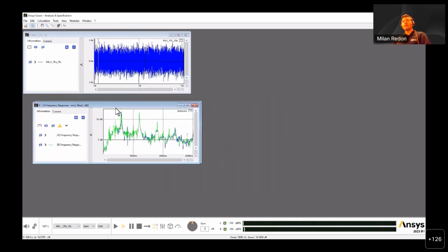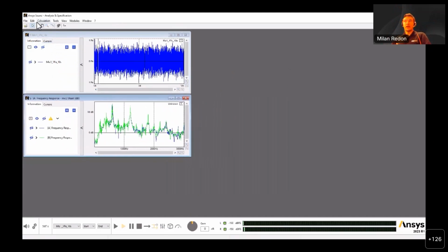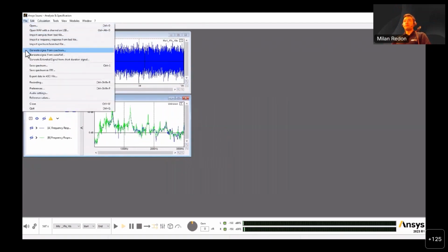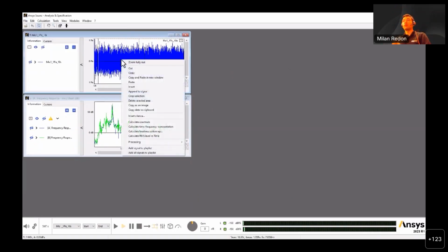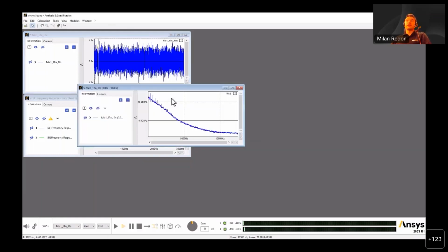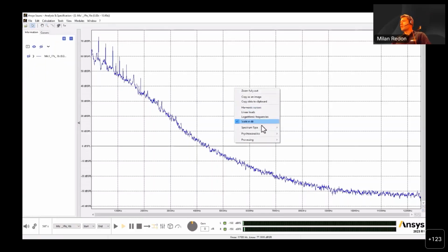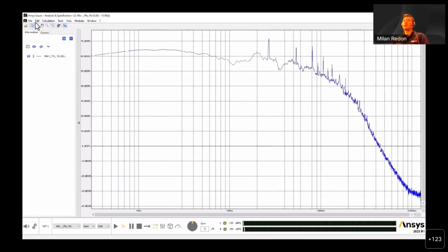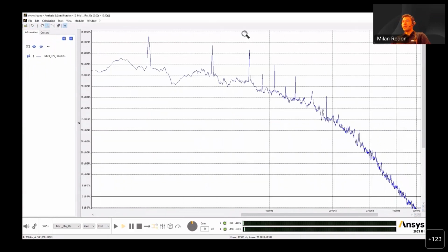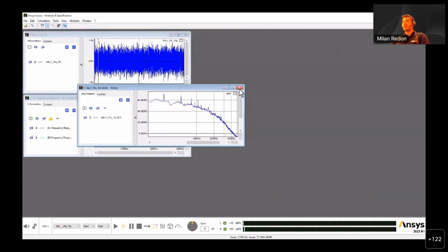And after you load your data, you can do this standard analysis. Here you can also generate a signal from a spectrum, generate a signal from a waterfall, but you do this standard analysis where you first calculate a spectrum in different formats. I saw a question about how to calculate dBA from dBSPL. So here you can do it. You can switch to dBA in spectrums. You can switch to logarithmic frequencies and then place cursors and see the values, etc.